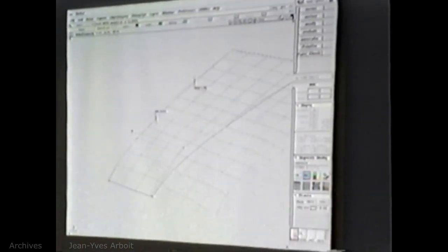Paul, can I ask you a question? Yeah. Is that building that surface based on the cross-sectional data? It is based on my getting feedback from the screen. So one of the things I want to do is pick the center line section and the surface at the same time and say scan deviation. It's going to turn on the deviation along the center line. So I can continue to model this thing by moving this hull. And then that's not enough control in order to match that surface. So I'm going to increase the controls here and continue to model it and get feedback.